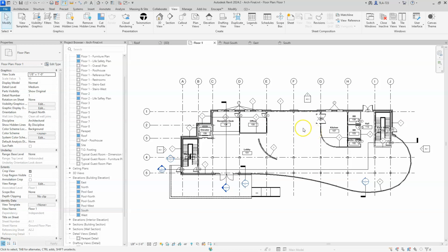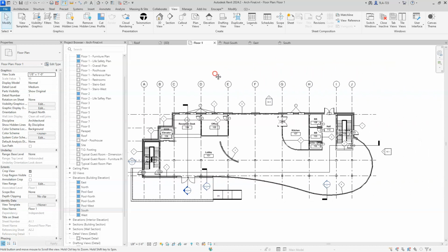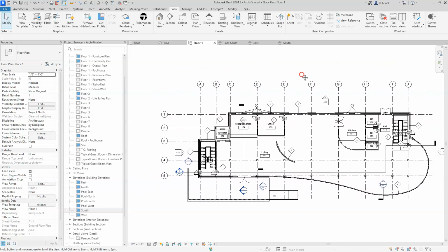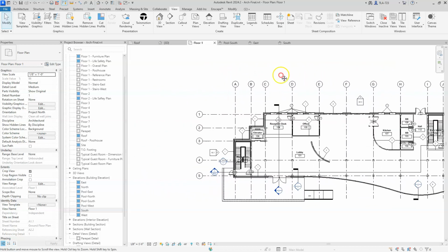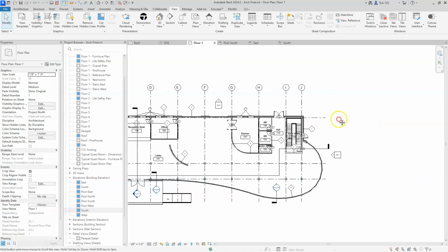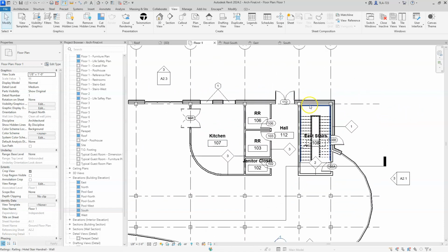So we know that we have the pan and the zoom, and that's our scroll wheel. Make sure, if you're not already doing it, you're using a mouse with a scroll wheel and a clickable scroll wheel. So when you push down on that scroll wheel, it should click, and that allows us to drag the view left and right. Now we're not actually moving any geometry, we're really just moving ourselves back and forth, right? But this allows us to pan across and see different things on the drawing, and that's most useful when you're zoomed in.